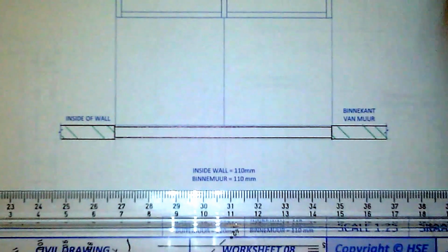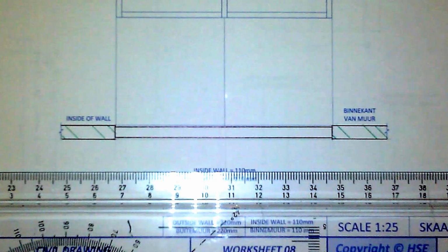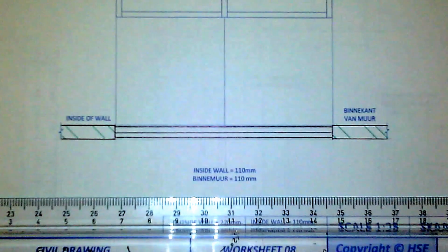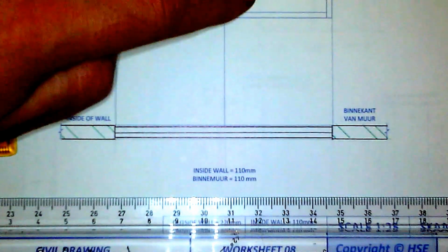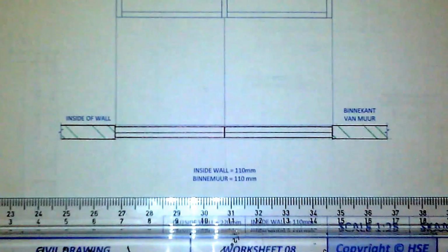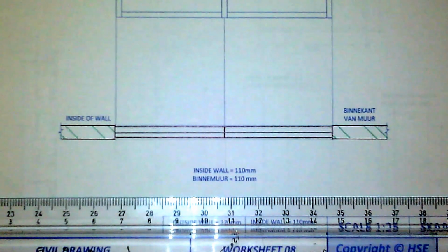Right, so it's almost identical to the thickness of the wall, and then all you have to do is add a line in the middle. Okay, and then you just take the center of the sliding door, which is coming down here, and add that in the middle as well to separate the two sides of the sliding door, and our sliding door is done. And that's the symbol for a sliding door. Remember, the design doesn't matter, we draw it symbolically. Okay, so let's quickly go to the sliding door for the outer wall, just to show you the difference.